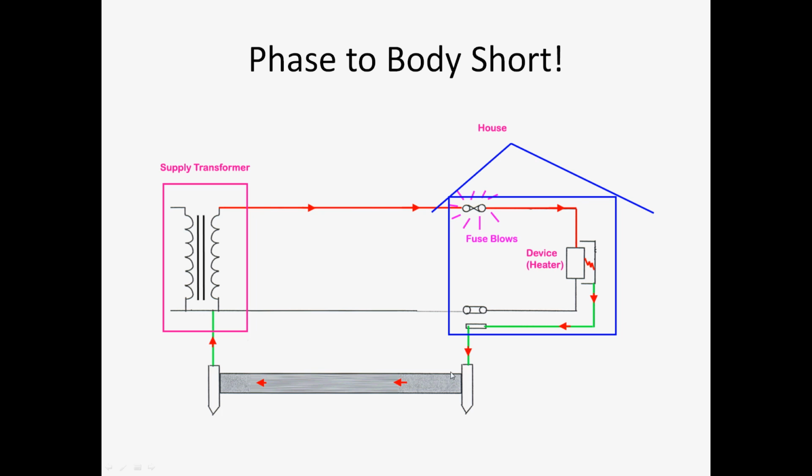Every house will have an earth electrode. And you may be aware that the earth is a good conductor of electricity, so the current will continue to flow even if there is no wire. It will continue to flow to the supply transformer. But you may note that this arrangement depends on the earthing system. Sometimes this earth wire may continue up to the supply transformer. Such a system is called TNS system.